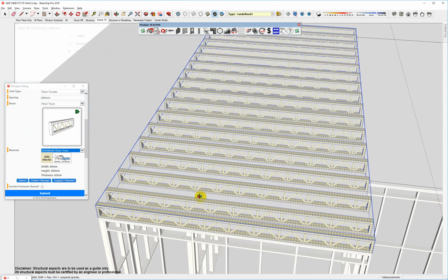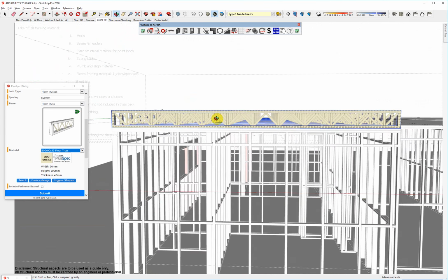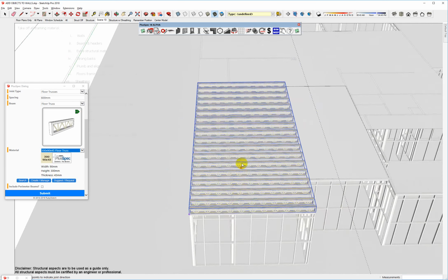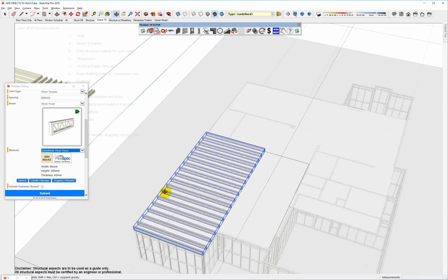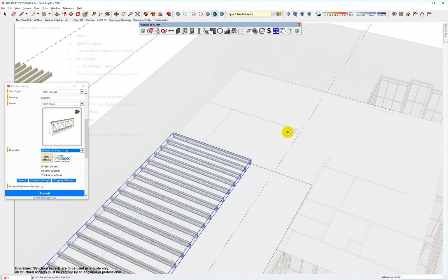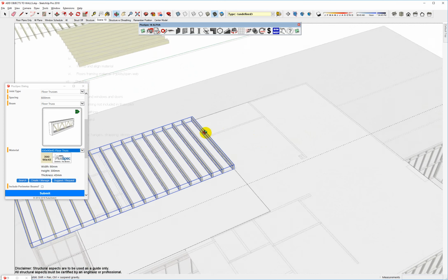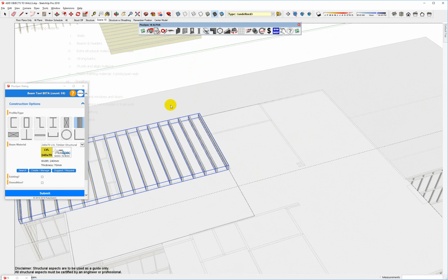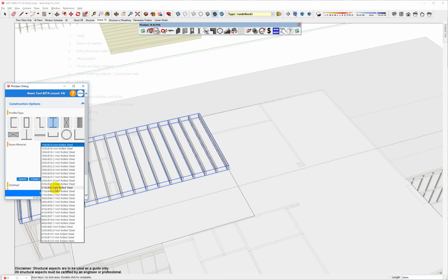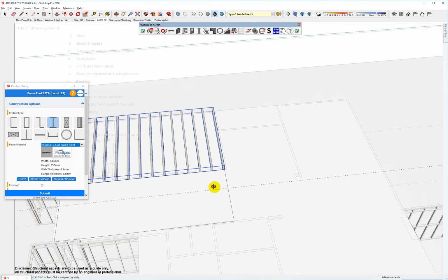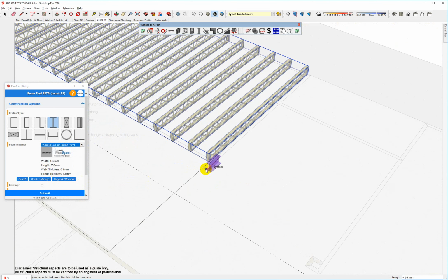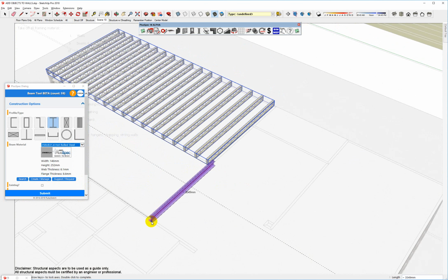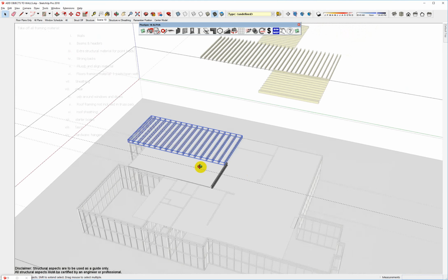Right, and now you can see that I have floor trusses in there, and I can also figure out where my penetrations may go through, or my piping, or HVAC, or whatever it is. And here I know that here's my maximum span of this particular type of joist. I can put another beam in, so I might go to my beam tool, add a beam and another beam, then distribute that load through the frame. It could be steel as well. Right. Choose UV. Obviously, if you're synced with the US catalog, it's going to give you imperial beam sizes. Right. And so on. Now I can basically do a bill of quantities from this.